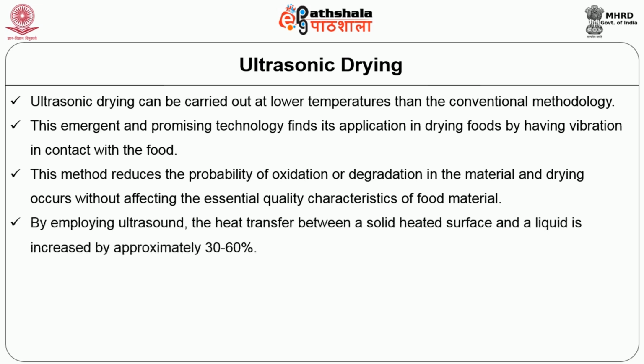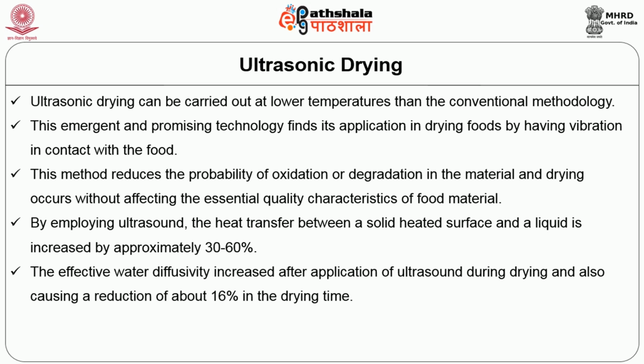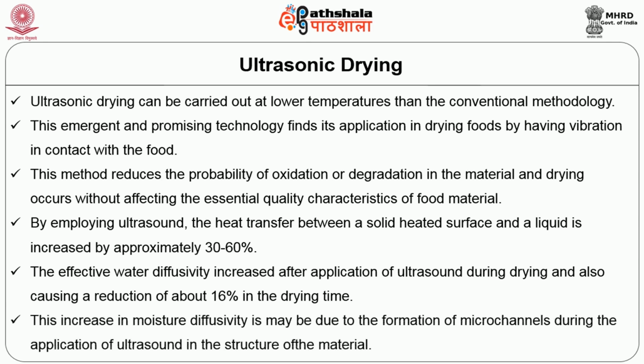By employing ultrasound, the heat transfer between a solid heated surface and liquid is increased by approximately 30 to 60%. Also, the effective water diffusivity increased after application of ultrasound during drying, and it also causes a reduction of about 60% in the drying time. This increase in moisture diffusivity may be due to the formation of microchannels in the structure of the food material during the application of ultrasound.